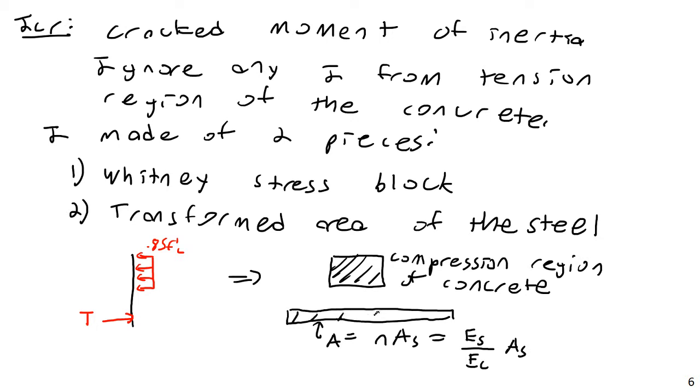You get two different areas, and you just combine them using your parallel axis theorem. And you can just treat this like a line area. Treat it as a single depth. You could calculate the local moment of inertia of that, but you can just use the A d squared, and that would be close enough for that.